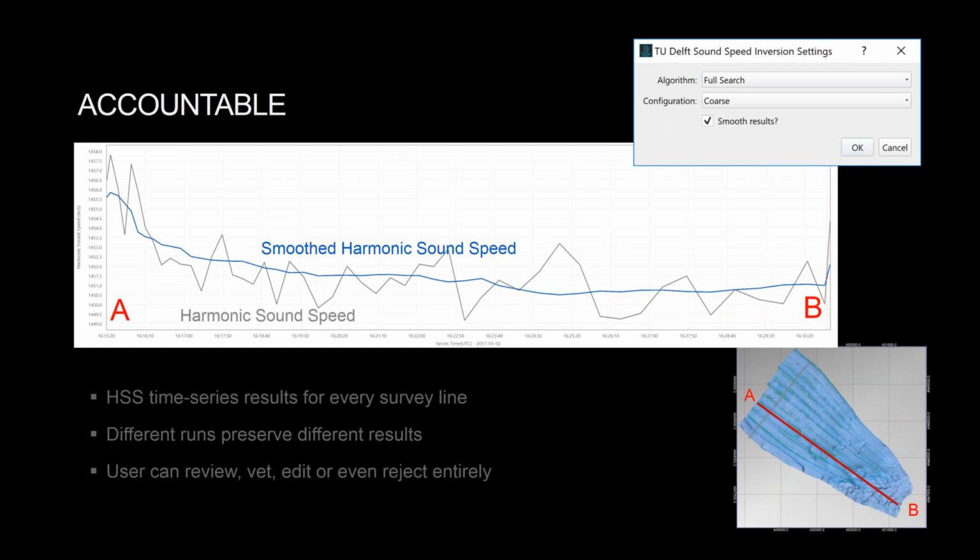It depends on where you're going to process your backscatter data. I'll answer from our point of view with QPS workflows. If you went to Fledermaus Geocoder Toolbox, also known as FMGT, the GSF files that we create would have better georeferencing. So the sounding footprint for each beam would be in a better spot. The depth values don't typically have much to do in isolation without the context of surrounding depth values. They don't really influence the backscatter correction that much. Where it would improve things is if you were doing a terrain model correction to improve the insonified area portion of the backscatter corrections. You would see an improvement. I don't think it would be very much. In fact, I'd be guessing that it would be hardly noticeable at all. Backscatter just isn't as sensitive to this type of artifact as obviously the bathymetric results are.